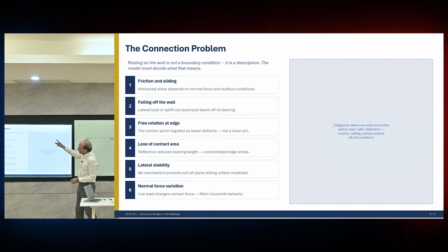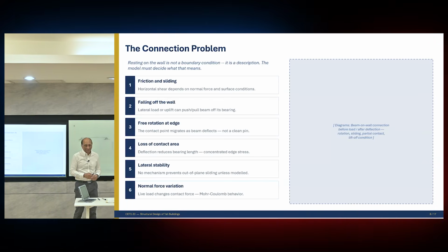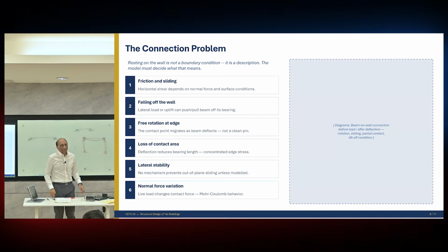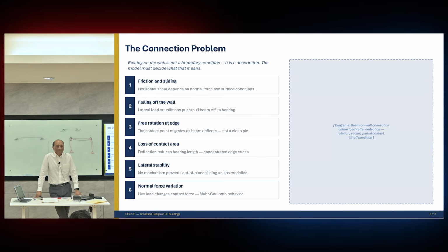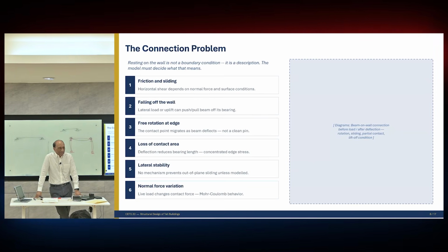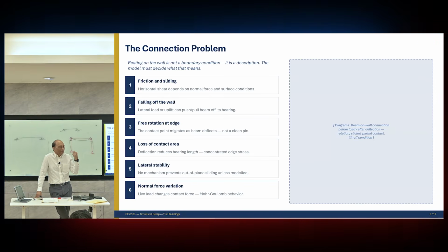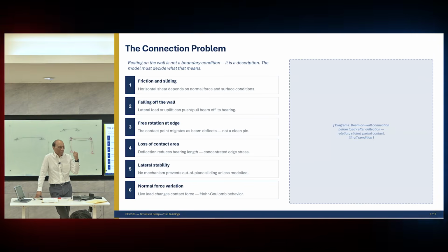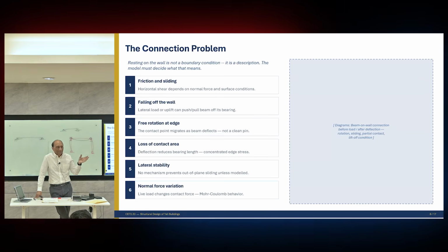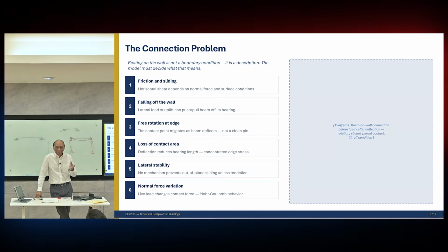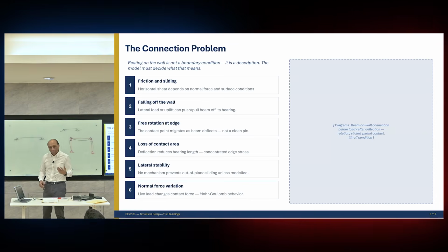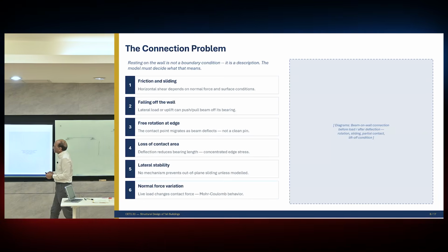So the connection problem is a serious one here. As you can see, this is much more important in bridges because in buildings, normally things are connected. The previous example is more like a bridge where things are just lying there, like a bridge girder on a support, and things are all disconnected and still transferring forces. So the connection problem, and also in steel, sometimes it's like that.